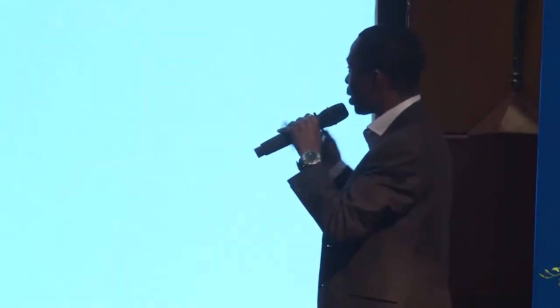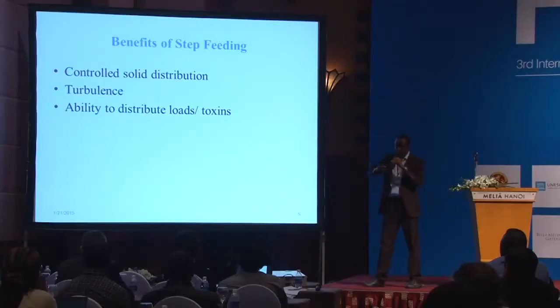Another benefit in step feeding is that it gives you turbulence. So I talked about the fact that mixing becomes a challenge. But when you step feed, as you introduce the material stepwise into the digesters, turbulence is created, and that enables mixing.